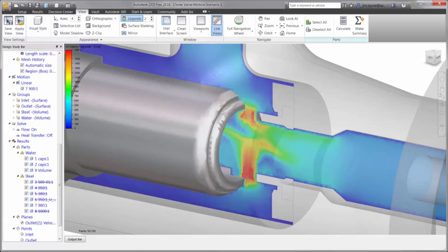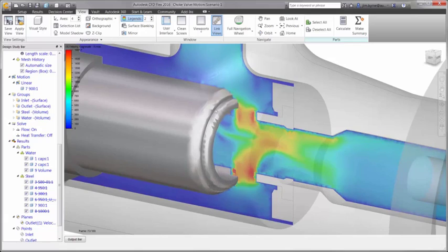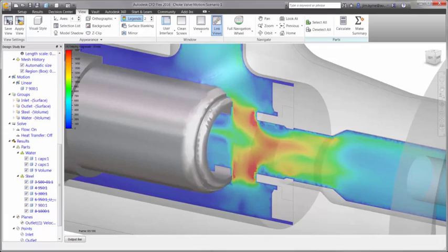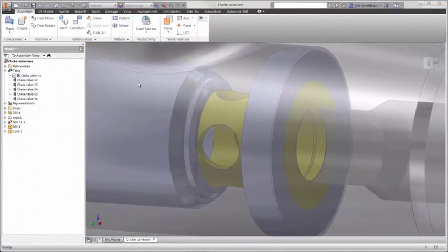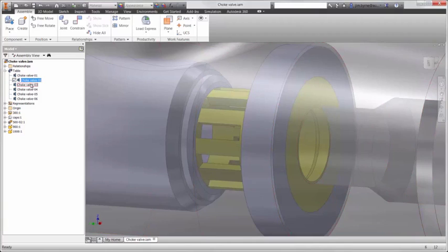While this design has been modeled in Inventor, users have the same ability to launch designs to the CFD environment from SOLIDWORKS, ProEngineer, or Creo. On the inside of the valve, you'll notice a cage that has been inserted for a few reasons. This will make the flow more symmetric, it increases frequency levels, and directs bubbles due to cavitation away from the walls of the valve body. In the end, it will extend the life of the product and reduce maintenance costs.